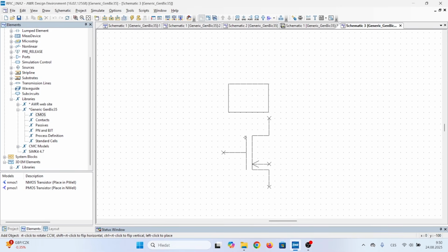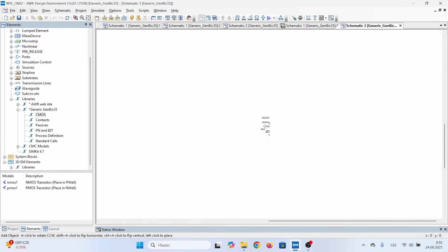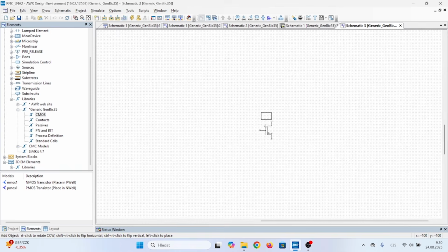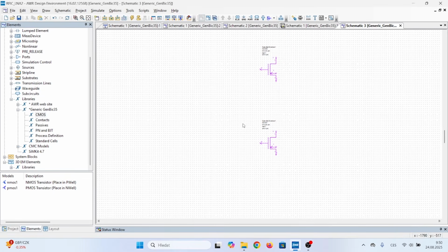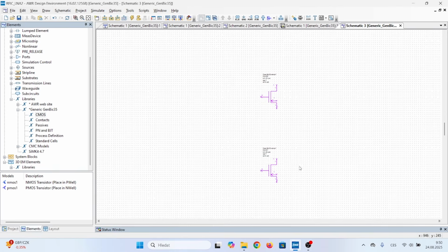So if you have a PDK, you need to import it here and use your PDK so it is manufacturable with your library. So this is our first transistor. We can copy this one and add a second one. We also need two more.